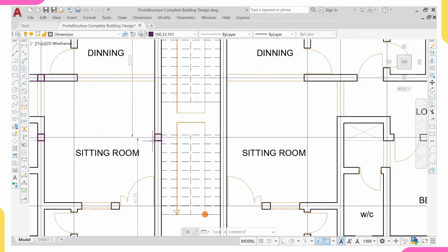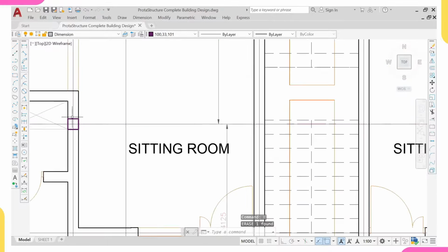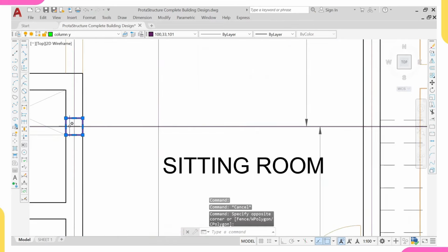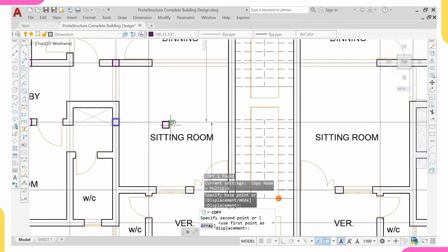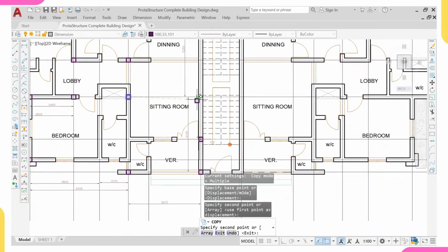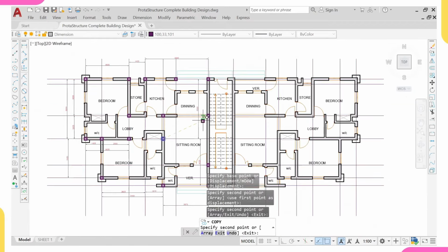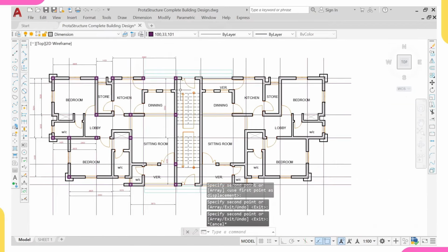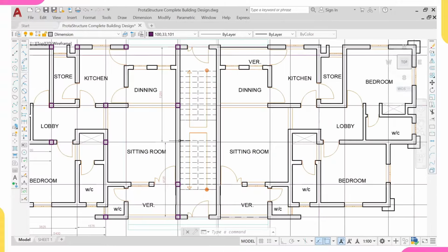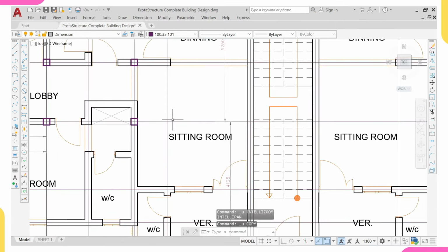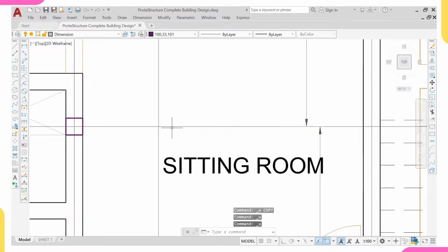But assume I remove this column now, enter, and then copy this one. Assume I remove that column, and I'm having something of this nature. I placed a column here and I placed a column here. That means I'll be having 2Y16 here, 2Y16 here, and 2Y16 here, which is normal. But since I've removed this column and just replaced it with only one here, that means I might have 3Y16. Do you understand? Let me do Control Z, Control Z, and also Control Z.